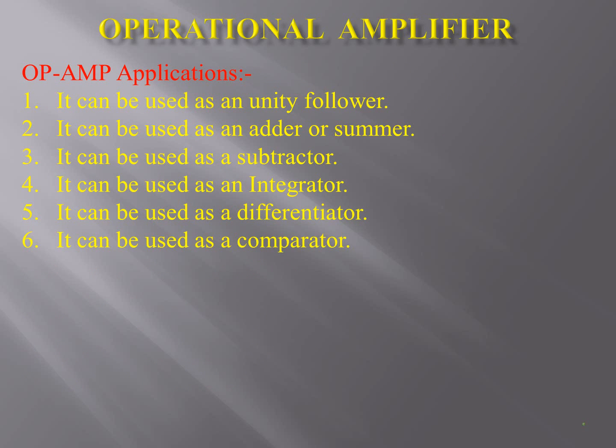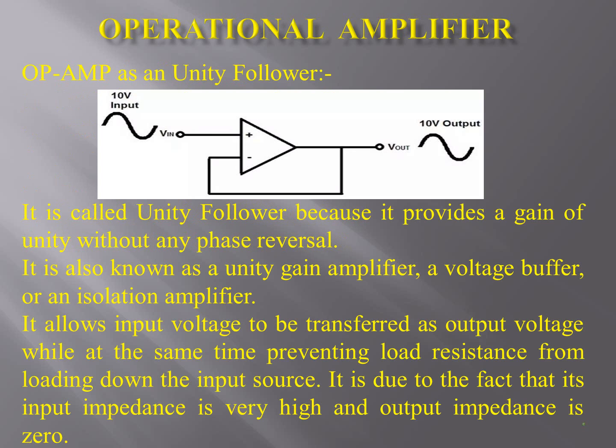Now, applications of op-amp. Operational amplifier can be used as an unity follower. It can be used as an adder or summer. It can be used as a subtractor. It can be used as an integrator, as a differentiator, and as a comparator. Now, op-amp as an unity follower.